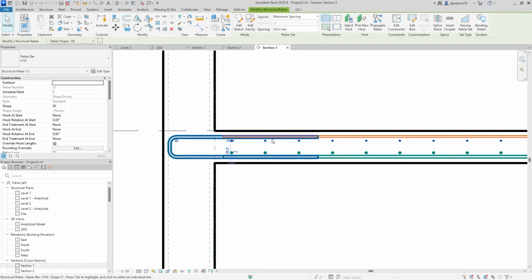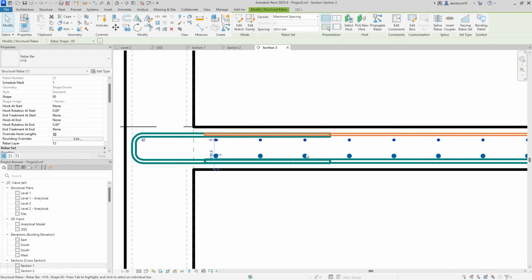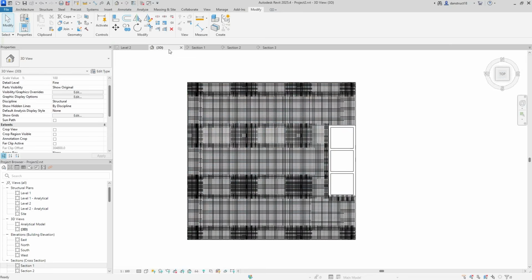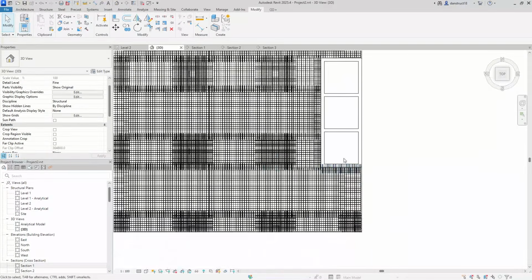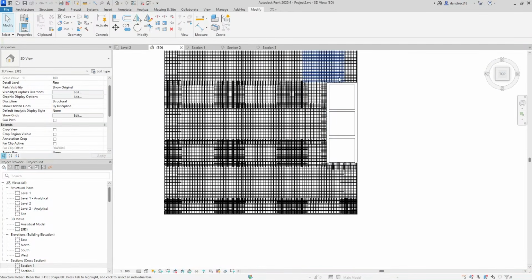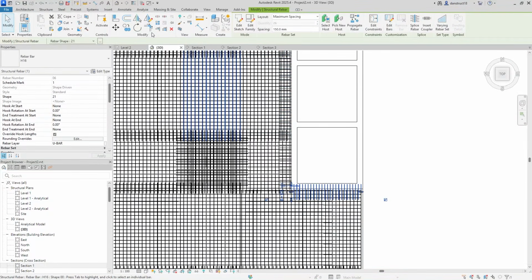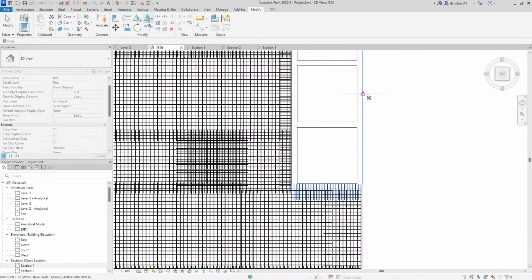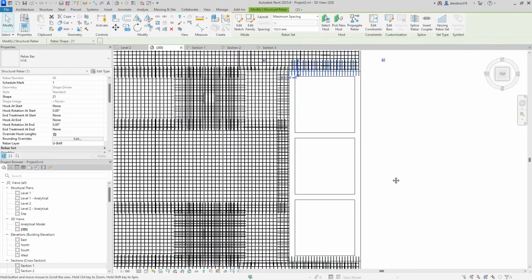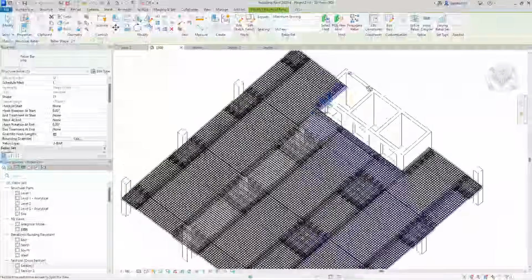This bar already here is T2. It's already here. We could actually extend this one backwards here and then put here this reinforcement, but that may not be reasonable or practical. You might as well just have this B2 run all the way to this point here. All right, good. So we've gone ahead and placed it in this direction, and we might also want to place it, of course, rather we'd want to place it in this direction. So I'll select this U bar like this, and I'll come here and click on this button, mirror draw axis, and now find the midpoint here, move in this direction, click, and just like that, you've seen we place it on the other end. All right, good.